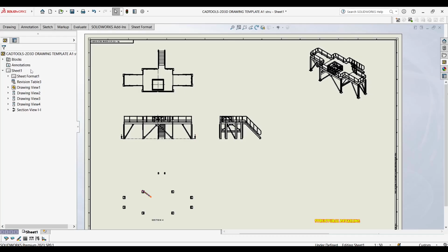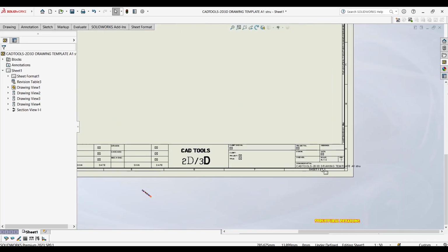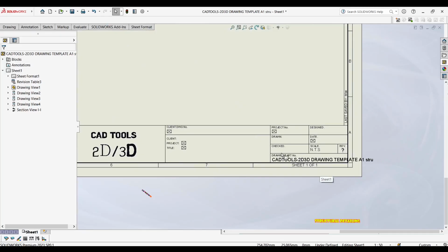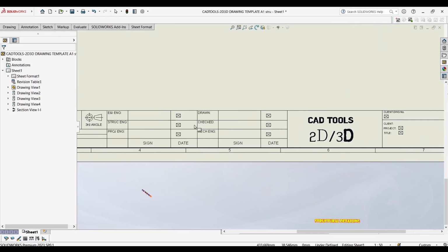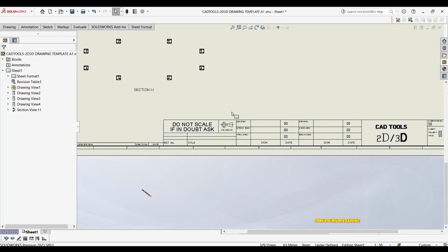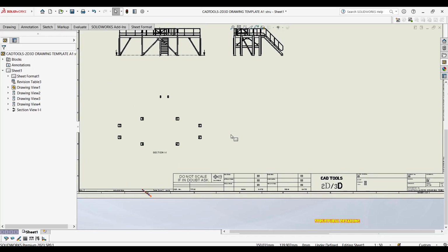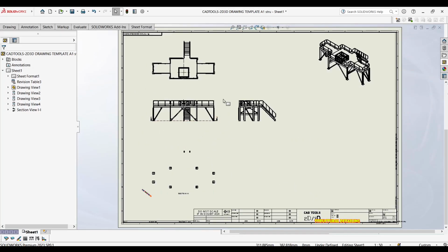I think it's the better method, because it tells you the sheet scale that's also written somewhere on your sheet. If you have a sheet scale on your borderline, you can link it there, and it says exactly what the sheet scale is for the next person who's using it, maybe on AutoCAD or 2D drawings, or any other software like DraftSight as well.